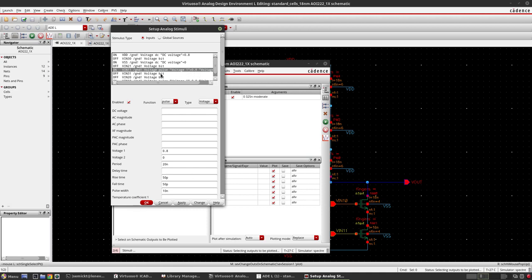So then V20, we have to give enable DC pulse the function and we'll give 0.8, period will be 40 nano, then rise time 50 pico, fall time 50 pico, pulse width will be half of 40 nano, which is 20 nano, 50%, and yeah, that's it. I'll click on apply.